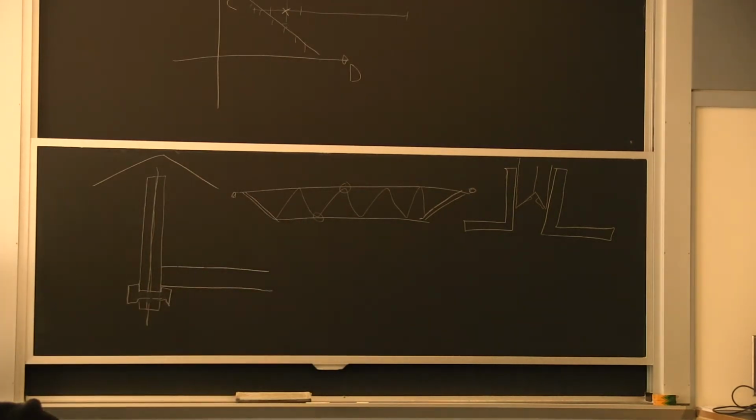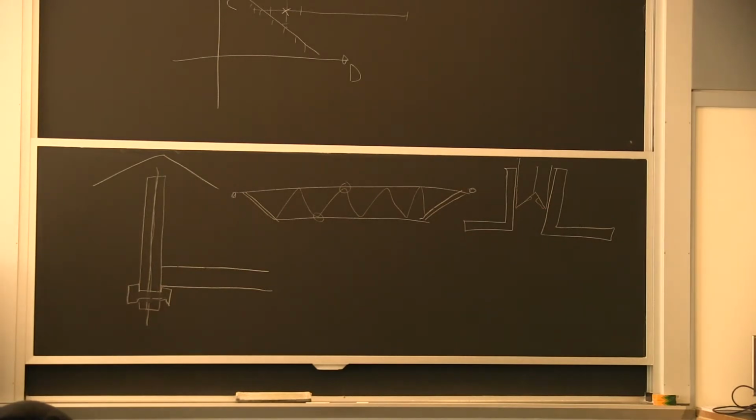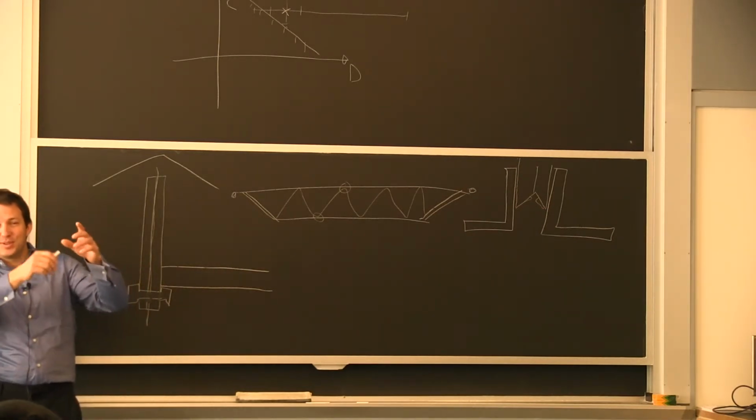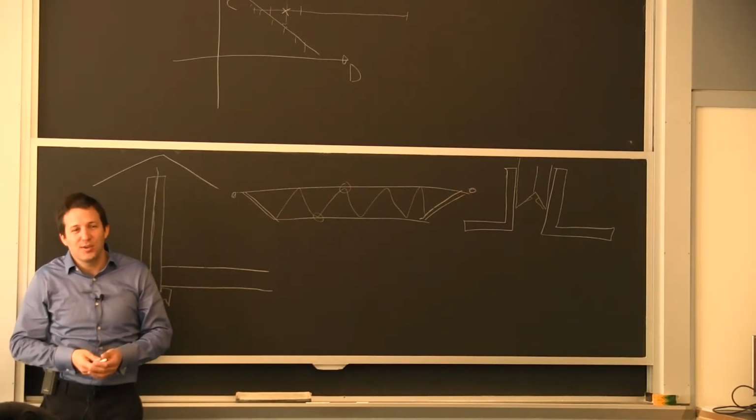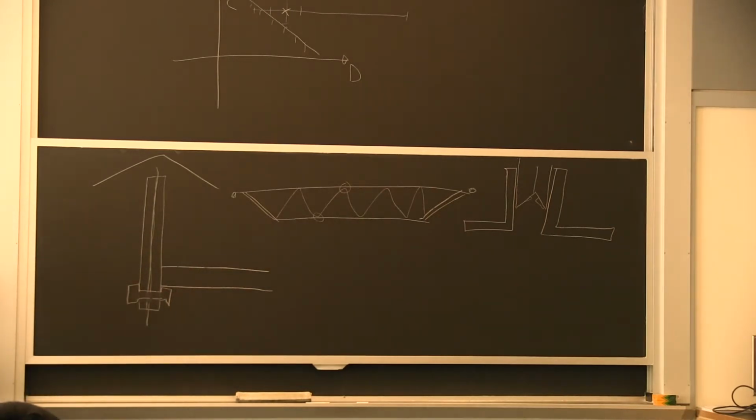This detail here is very different. This was all tubes. So you have a tube chord, and that's what we're looking at down here, the tube diagonal. It was cut on an angle. That's how it's done at Logan Airport. You look at all these tubes and they have all these welds. It looks great. It's just not exactly what is going to give you the maximum strength. I don't know if you see clearly on your handout, but what I'm looking at here is rusty steel that is exactly the profile of the original tube. So the only place that I had fusion here, that I melted the chord, is this little piece in the corner here, and then I have another little piece there, maybe a little piece here.